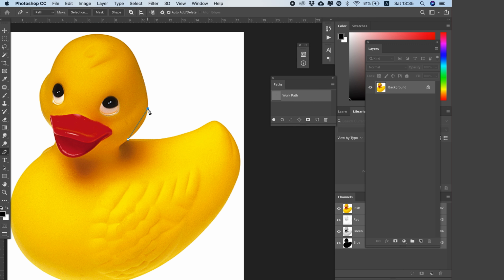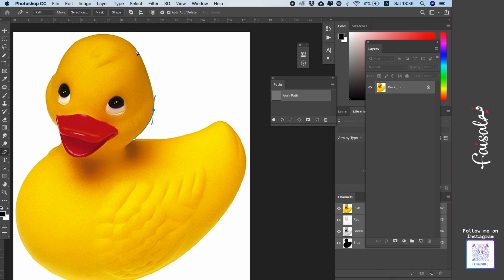I click, and now the line has become a straight line, and that doesn't fit the shape in front of us or the curved line or shape. So I go back to it, click again, and while holding down, I drag upwards like this using the mouse. Alright, that was how you define a curved shape, a circular shape, or any shape that isn't straight. Now I just continue as usual. I keep going the same way, click and drag, click and drag.